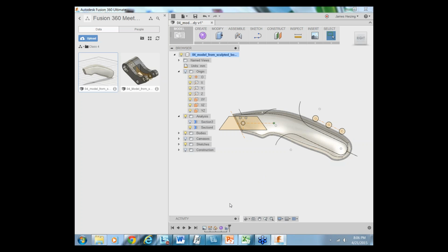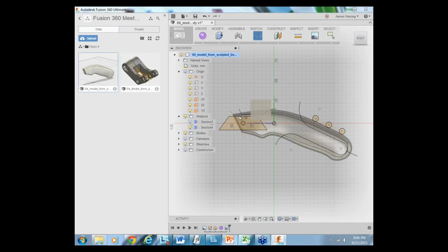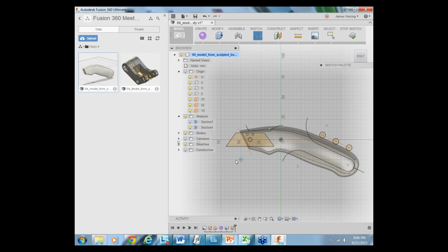All right, so what are we going to do? We're going to create a sketch, and we're going to sketch a line. So under the drop-down, we choose line. And we're going to choose this nice plane that's parallel. The one that highlights like a plane in the middle of our thing, just click on that. And now that's defining where we're going to sketch this line.